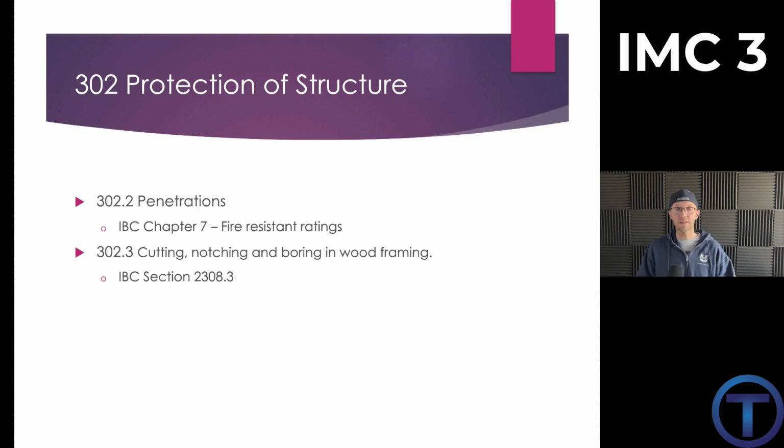And because of that, there are lots of details. Now, this is one of the sections in the 2024 that has been kind of redone, and there is one of the QR codes in there if you want to have a look at that. But rather than reprinting all of the standards about penetrations, cutting, notching, boring, the wood framing, all those things that are listed as to what we can and can't do, they've put that over in the International Building Code, in section 2308.3. It spells out what we can and can't do as far as putting holes into studs or joists or other things like that.